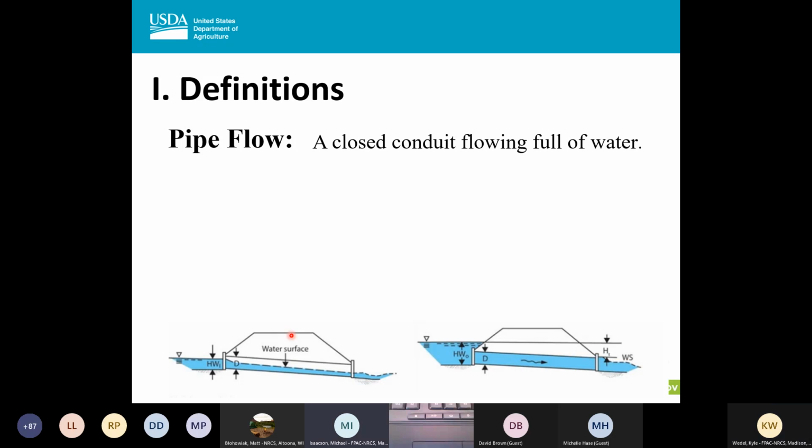Yep. One more question on the weirs. If you could go back to the slide on the weirs. When you have a free flow weir, that is upstream control on a flow direction. But when you have a submerged weir, that's a downstream control, meaning the water backs up into your weir, and that's why you have a reduced flow. Is that correct?